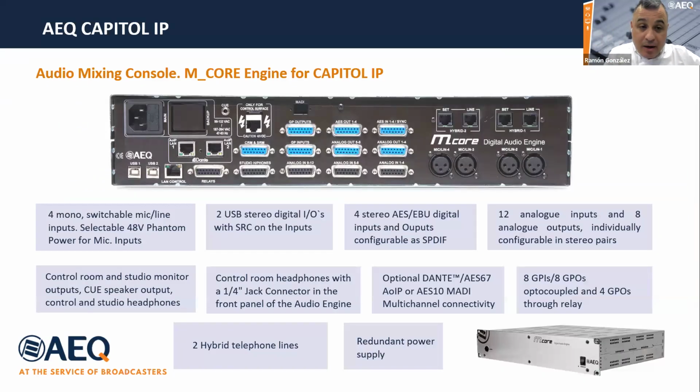Okay, this is the back of the engine. First of all, we have four inputs and outputs for microphone or for line input signals. We can provide as well phantom power for condenser microphones. Two USB input and output, four stereo input and output for AES3 or S/PDIF if you need it. 12 mono analog inputs and 8 mono outputs